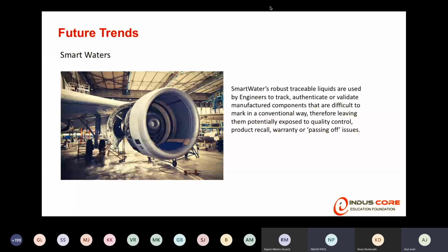But then again, as I said, there is a compliance industry. You need to get your hardware validated from two parties. One is the civil aviation authorities, and second is the aircraft manufacturers. Unless you get your hardware validated by these guys, you cannot put it into the system. So there are standards for the compliances. You need to make sure that your EM interference is low, which is not impacting your existing wiring system. Second, you are not emitting any unwanted frequencies which can be traced by your navigation systems. But nowadays, even most of the navigation systems are very, very robust.